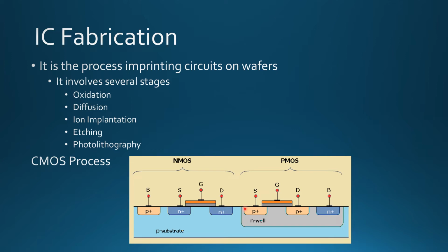The PMOS transistors are built in exactly the opposite way. But before that, we embed an N well, because we have to integrate the P plus diffusions, and we cannot do it directly on the P substrate. So we build an N-well inside the P substrate, and then we diffuse the P plus, and thus we get the drain and source terminals. The gate terminal is applied in between, with an insulator, silicon oxide, built to make the gate. That's how we build PMOS and NMOS transistors.